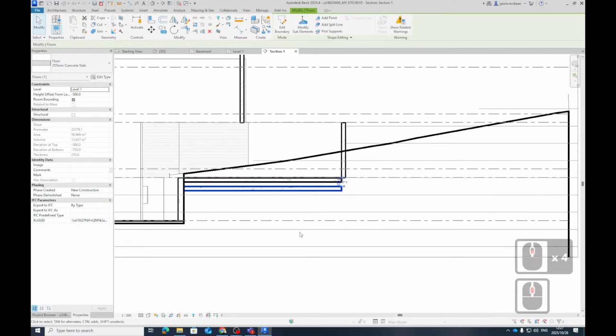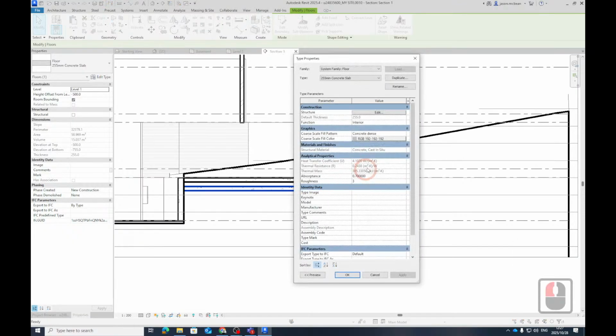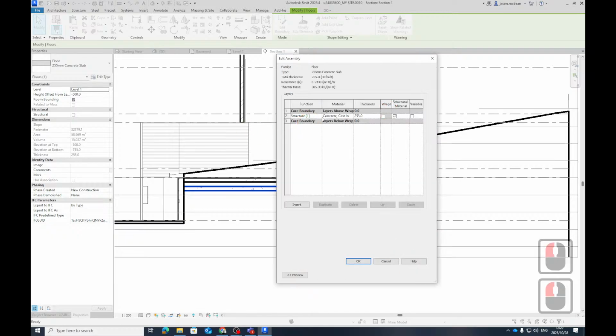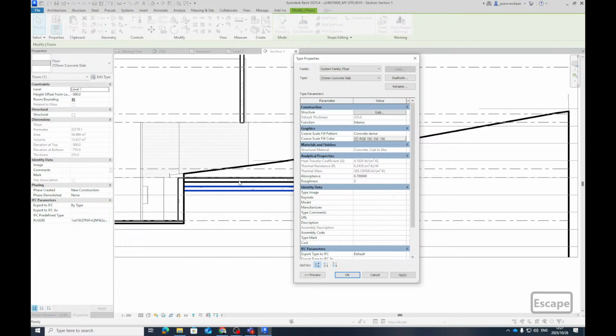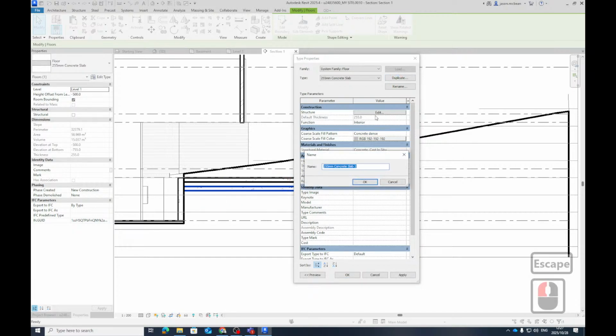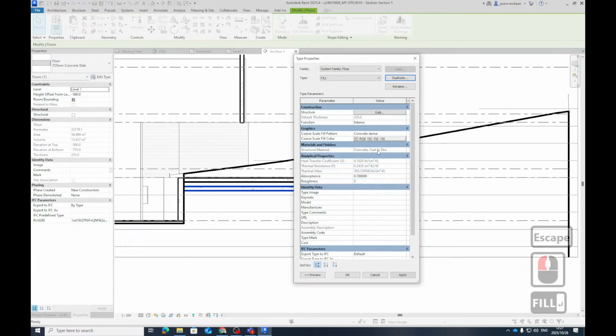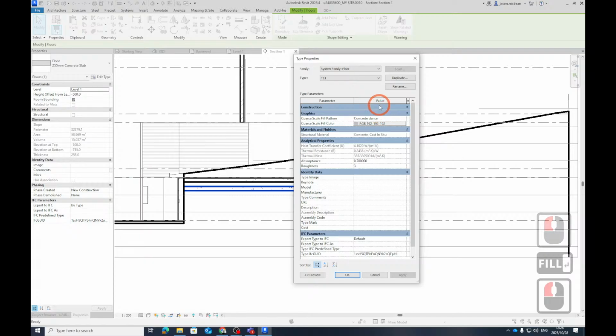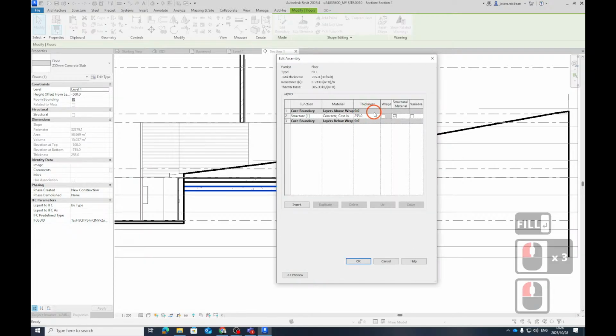That's why you don't need multiple levels. You just understand certain things must just be offset. Yeah, because it's only by like 500. Exactly. Because now if you've got these different levels, they're going to cut differently. It just gets so complicated. I'm going to duplicate this little floor slab. I'm going to call it fill. And I'm going to change the makeup of this to be 150 because fill gets done in layers of 150 mil. This will become finish.